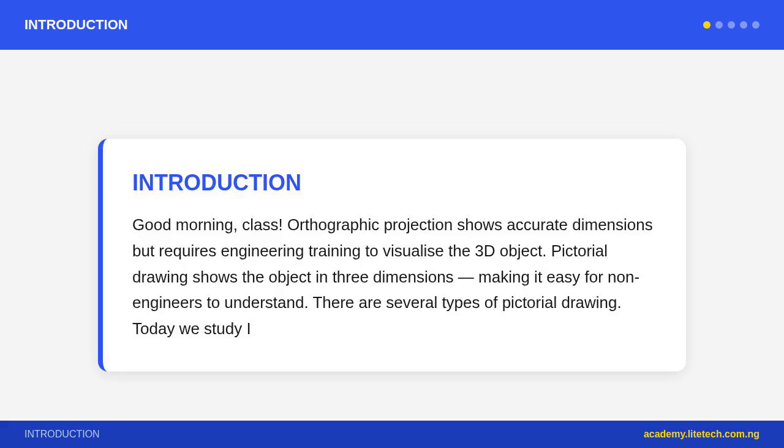Isometric drawing properties. 1. 3 principal axes, 1 vertical axis, and 2 axes at 30 degrees to the horizontal, 30 degrees left and 30 degrees right from the vertical. 2. True lengths. All lengths measured along or parallel to the 3 isometric axes are drawn true to scale, not foreshortened. This is the key feature of isometric drawing.